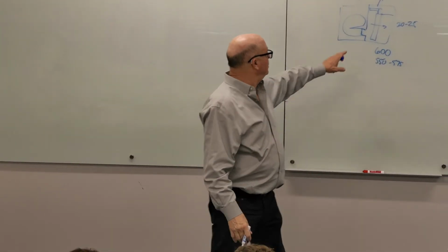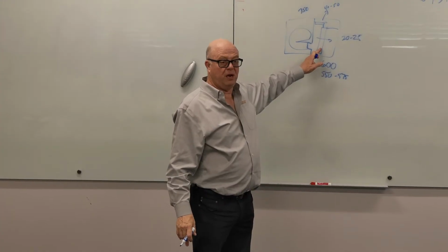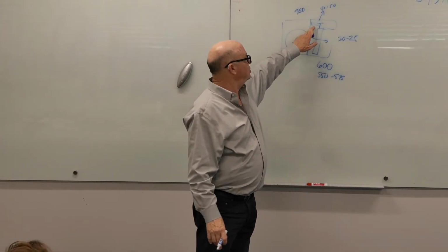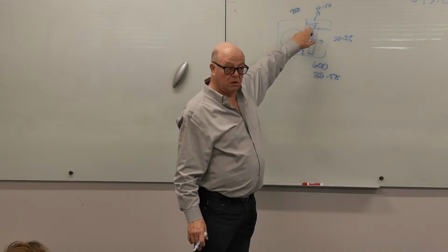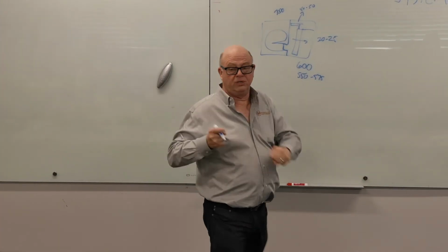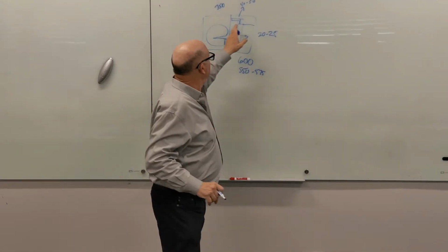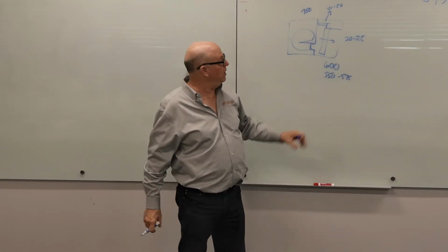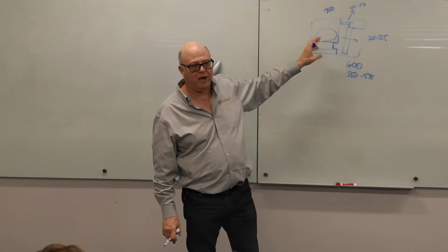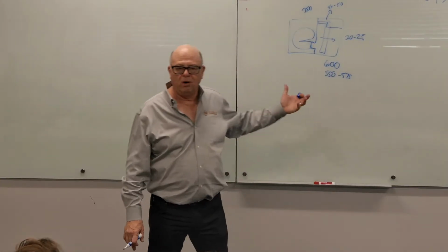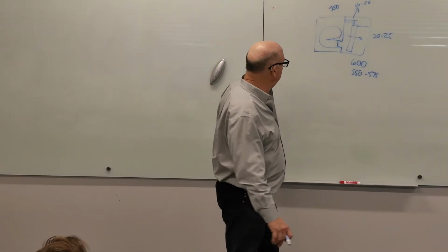And this is probably a 6, maybe an 8-row coil. And this is a 2-row coil usually. So the pressure drop is a lot less. So you can get away with a much smaller coil, and I've drawn it that way, and that's not grossly out of scale. That's more or less what it's going to look like to you in the field.